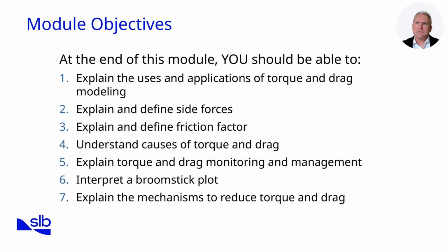On this slide, we see the learning objectives specific to sub-module 2 of our torque and drag discussion. By the end of this module, you should be able to clearly explain and define side forces, as they play a critical role in generating torque and drag in the wellbore. We will also cover friction factor, which is fundamental in modeling drag behavior and understanding how drilling fluids, borehole conditions, and contact surfaces influence resistance.